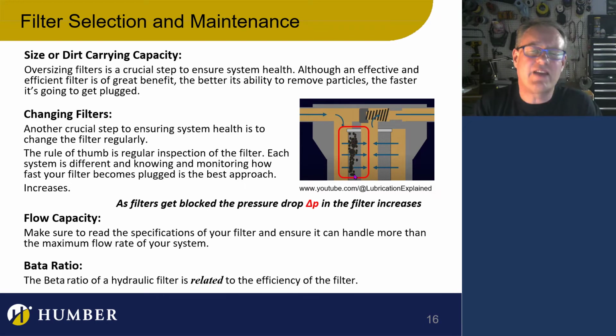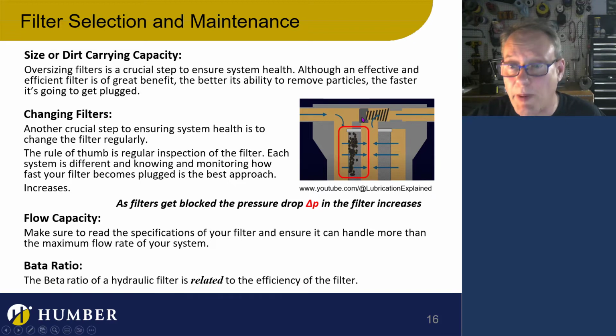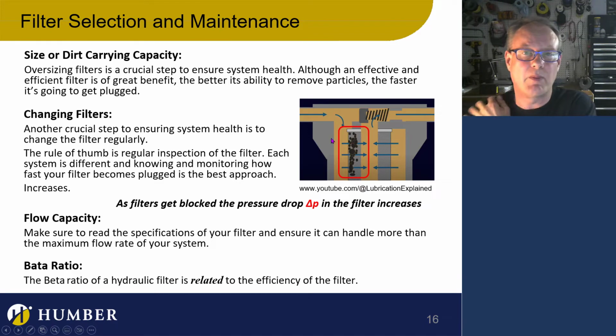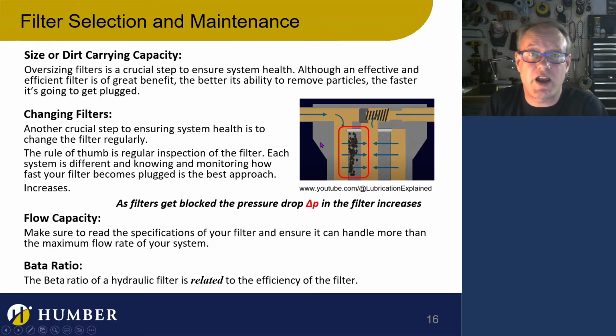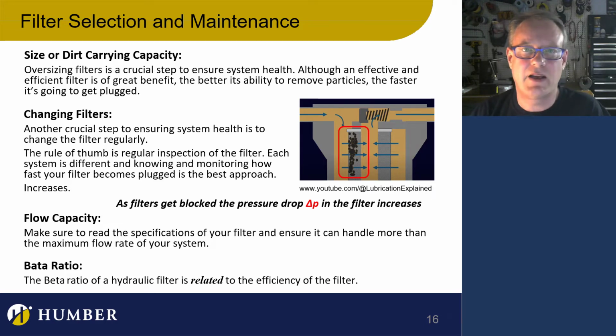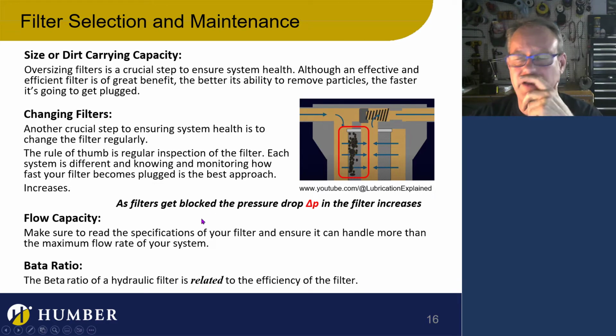So essentially any filter you put in the system is going to get dirty and it's not going to work as well, and if it's really bad, that check valve is going to open up in here and it's going to be a real problem. But the fact is, if you don't have the filter there, your system is totally destroyed and ruined. So you have to maintain the filters. You have to change them regularly. You have to monitor them regularly, and I will show you how you can monitor them in another slide.